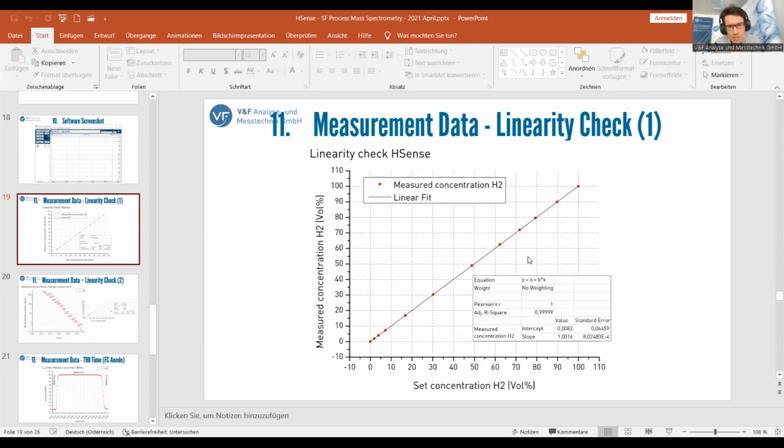As far as frequency of calibration goes, this is something that we can only suggest. The calibration typically takes roughly 5 minutes if you have both gases available. What I recommend to customers, if you have crucial measurement tasks, is to do a calibration before a run on an engine or on a fuel cell, since it doesn't take a lot of time. Then you are safe for at least the next 8 hours that you have reliable results from the instrument.